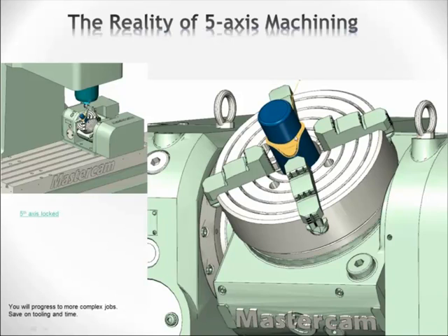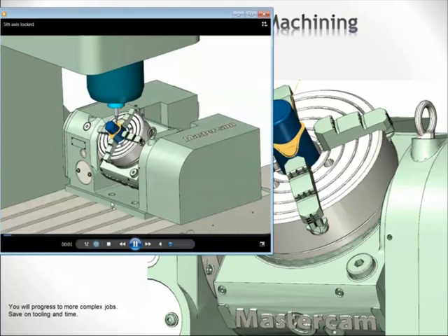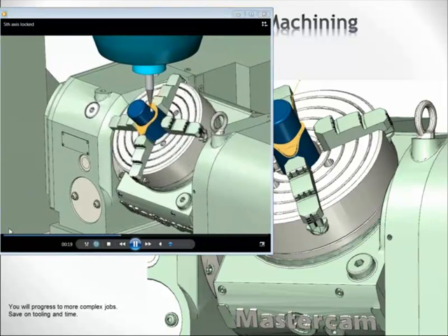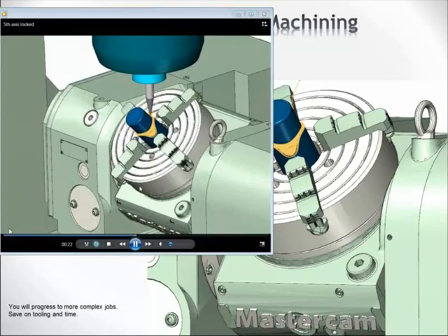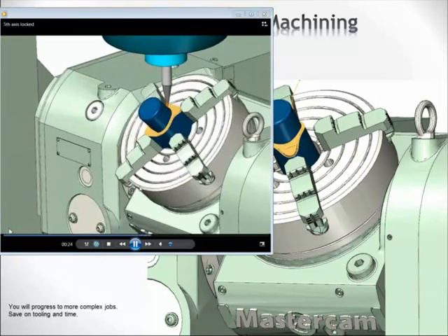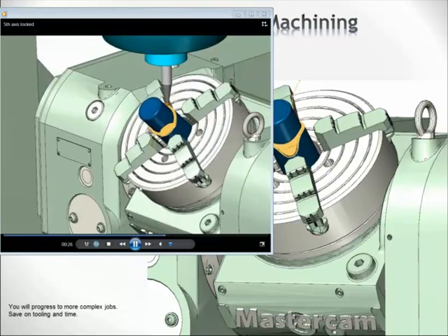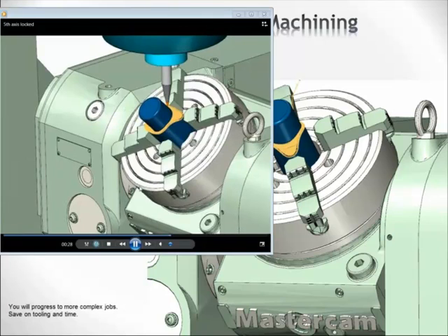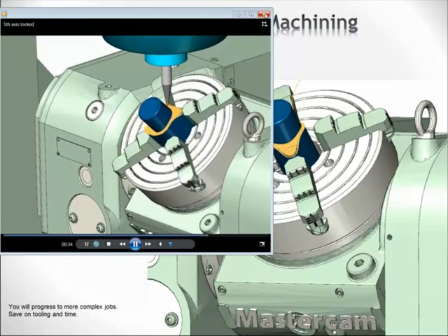Now, if you did this on a 3-axis machine, you would need a long, skinny ball nose cutter to cut that fillet. But if you're using a 5-axis machine, and this is really just a dual rotary device on a 3-axis machine, you could use a tapered ball nose cutter to get into that corner, so you have much better rigidity, much better finish when you're cutting something like this. Again, the toolpath is a spiral toolpath that machines that whole feature, that kind of skewed face.